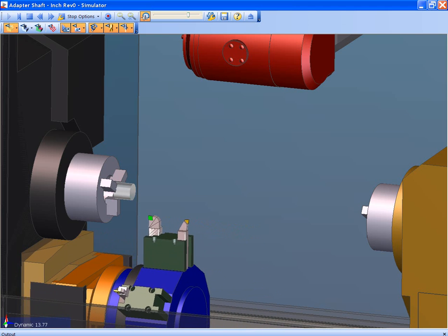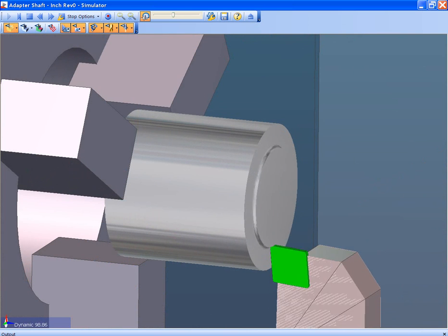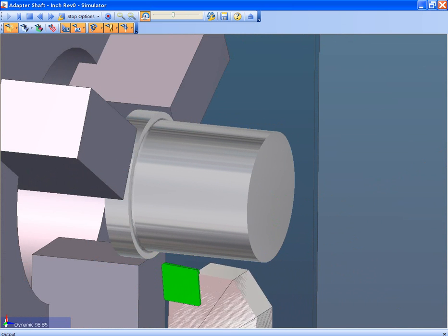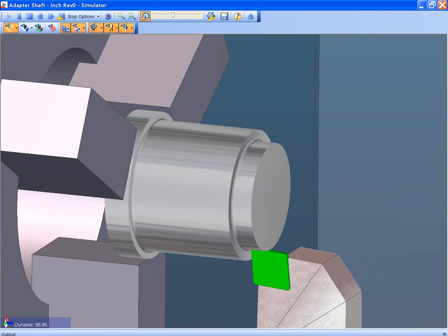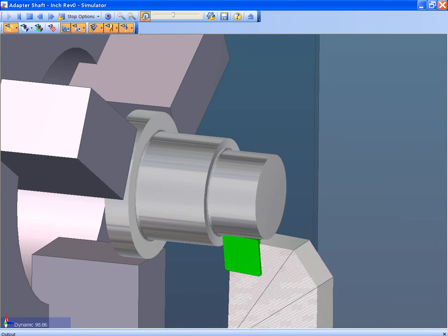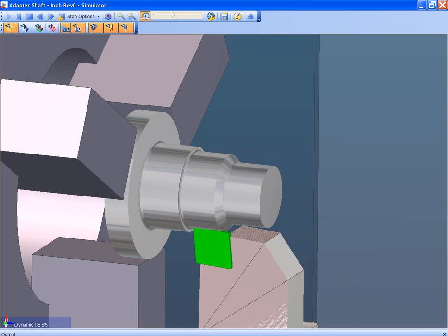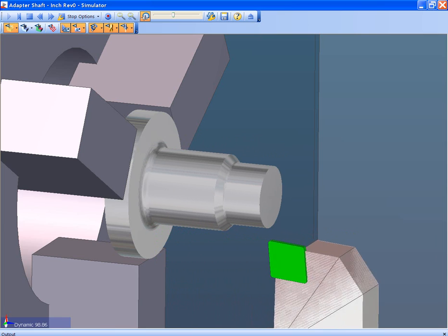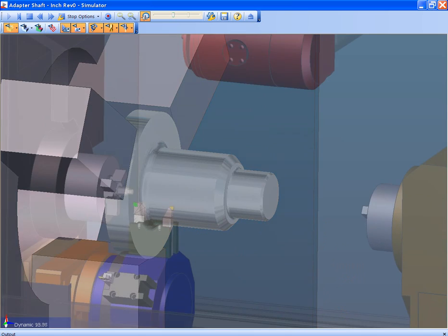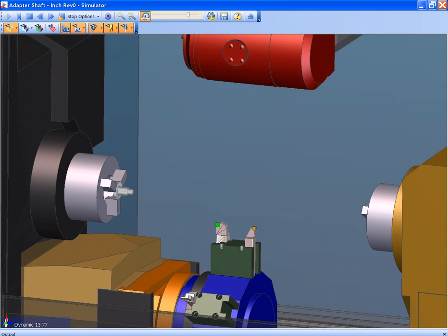Standardization is achieved by consistent tooling selection, speeds and feeds driven by the tool and the material, coordination of the spindle and turret timing, machine movements driven by the current part geometry, including any rapid and feed moves. Cycle optimization comes from the intelligence of the engineer using the power and the control of Edgecam. The in-process stock improves the cycle time by optimizing the tool cutting movements and only cutting the area that is required. Edgecam's control of the tool path allows you to get your part done in your machine the way you want it.